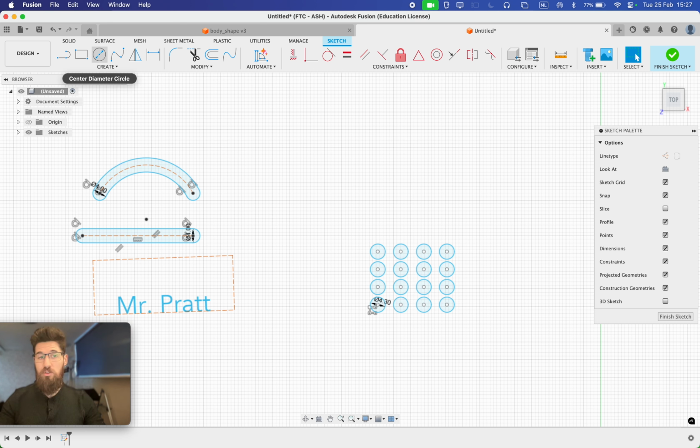For instance, you can make a circle here and then extrude it out. You can also add the built-in sphere feature, you could also use the built-in cylinder feature on extrudes. There's lots of different ways that you could do things. It just depends on what your specific workflow is. However, for rectangular patterns, I recommend you only do simple rectangular patterns inside of a sketch.